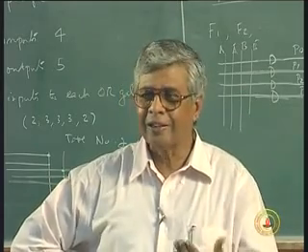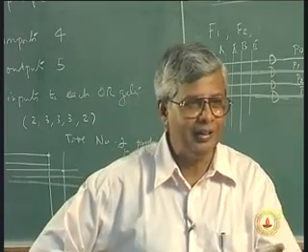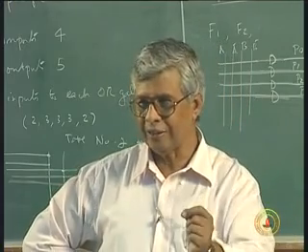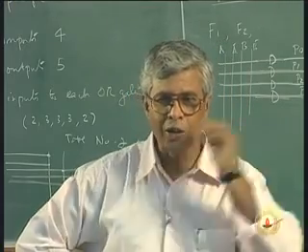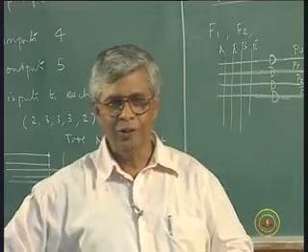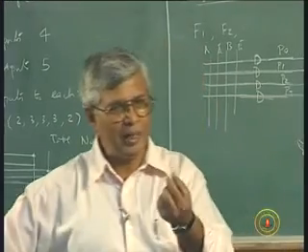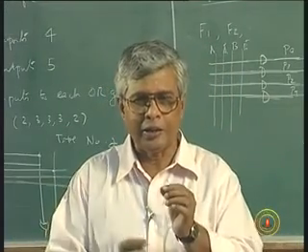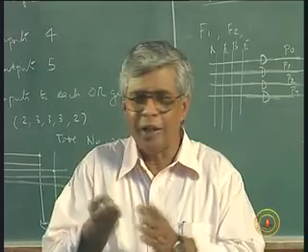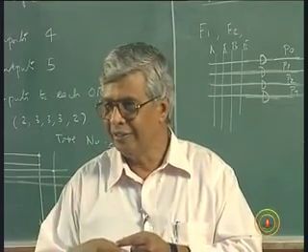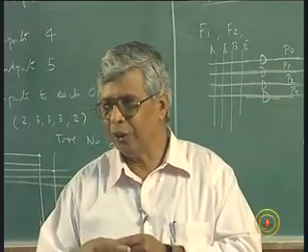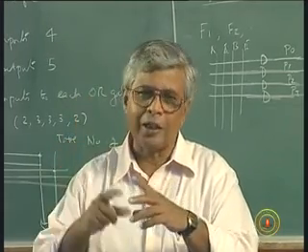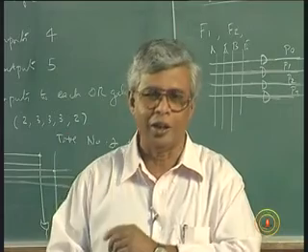It should have a mechanical ruggedness. It cannot be brittle. It has to be put on a base, which will stay. And then I have to make connections, because when I have 1,000 gates, naturally there will be a large number of inputs and a large number of outputs. So I will have to provide for all those inputs and outputs. That means I need a base with different pins for inputs and outputs, and the size cannot be micron dimensions. How do you physically connect it to another device or a computer? So I need to have a minimum size. So when the size becomes larger, all our original concepts of size saving, everything has to be rethought.